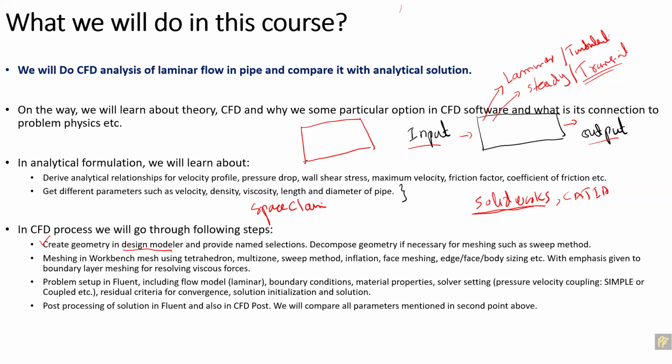These things are done in these geometrical tools in ANSYS. One more thing when you import geometry: the CAD modeling person might have made the geometry in this way. Sometimes they start from there. Sometimes they have done the geometry up to here, and the second part they may start from here in this way. This is okay for manufacturing purposes, for a CNC machine, but from the CFD point of view, they are two different surfaces. They're not connected and they are overlapping in some regions.